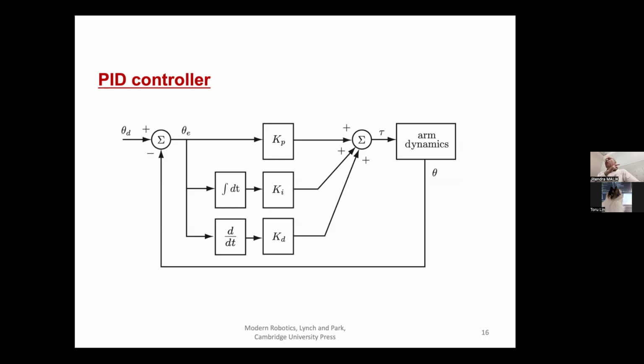So now what could go wrong? Okay, let's think about what could go wrong here. What could go wrong? So the natural answer is just keep increasing the gain. These Ks are sometimes called gains. So if you make the Ks larger, then actually it does a better job in terms of reducing the error. But no, it doesn't go on forever because at some point you get instability.